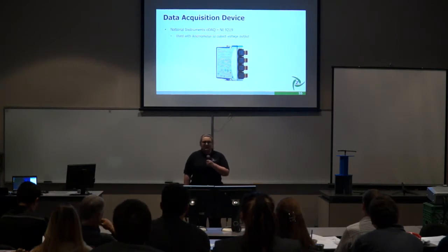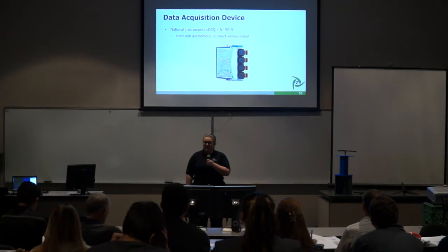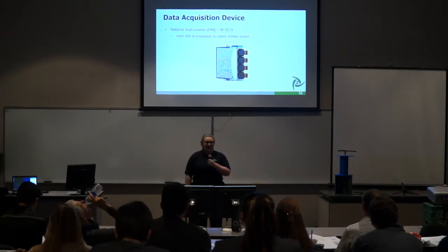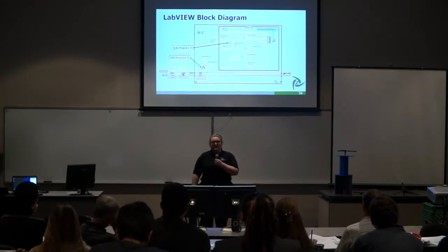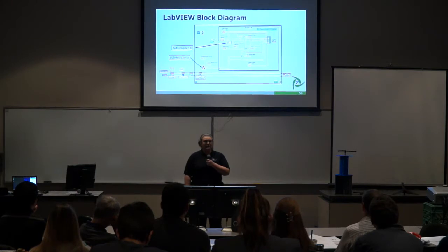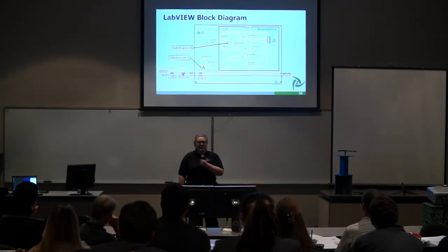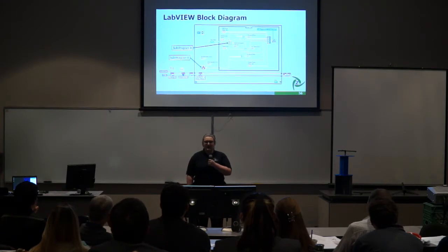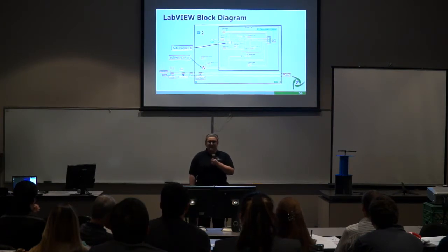The analog cup anemometer outputs a voltage, so the DAC will collect the output voltage and transfer that information to the computer. Project Zephyr has chosen to use LabVIEW for our data acquisition program. LabVIEW is a program that takes collection of data, converts the data into useful information, makes any necessary calculations, and displays the data as needed on a screen in real-life accurate time.